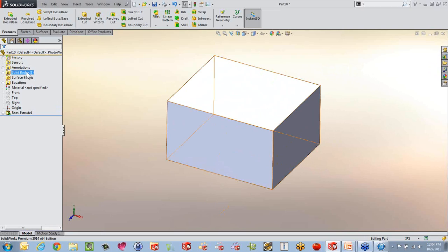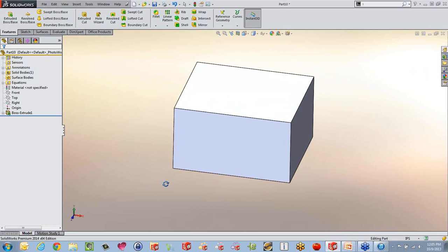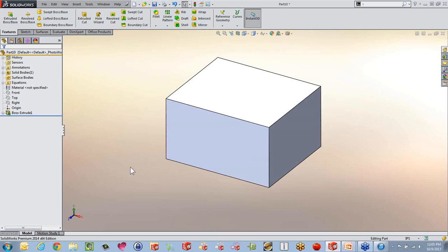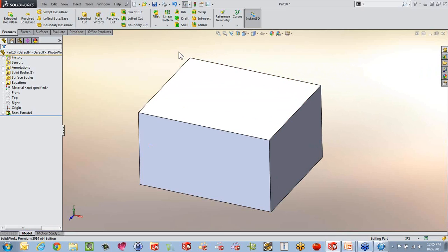It is true that we can use surfacing for making swoopy surfaces and things like that. But it's important to understand that surfacing is not really the finished result. The finished result is still a solid body. The only difference with surfaces is that it helps us create one surface or one face at a time. Where a solid body, as we can see when we use the extrude command here, literally just takes care of all 6 sides right out of the gate. With surfacing, it gives us an opportunity to handle each side individually, and that could give us the power of making some of these super surfaces and stuff like that. We can use it for other things too that I will show you within the next hour or so.